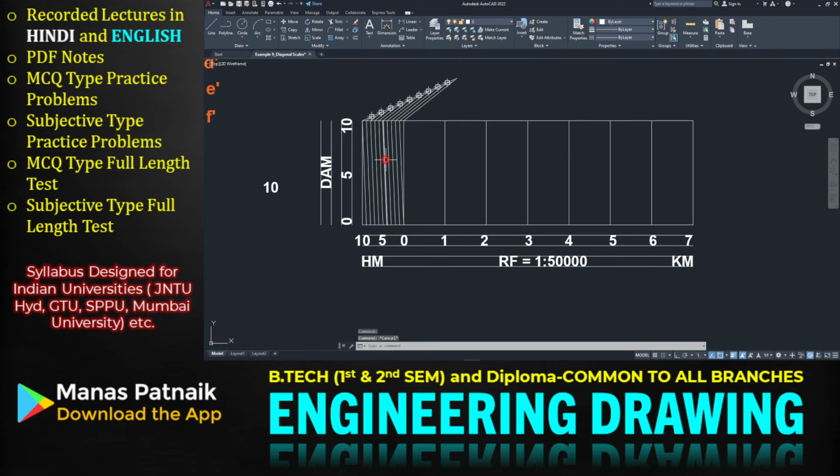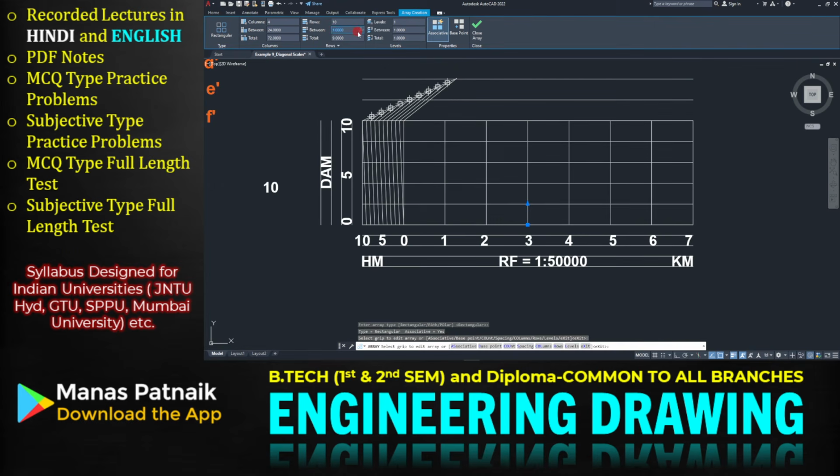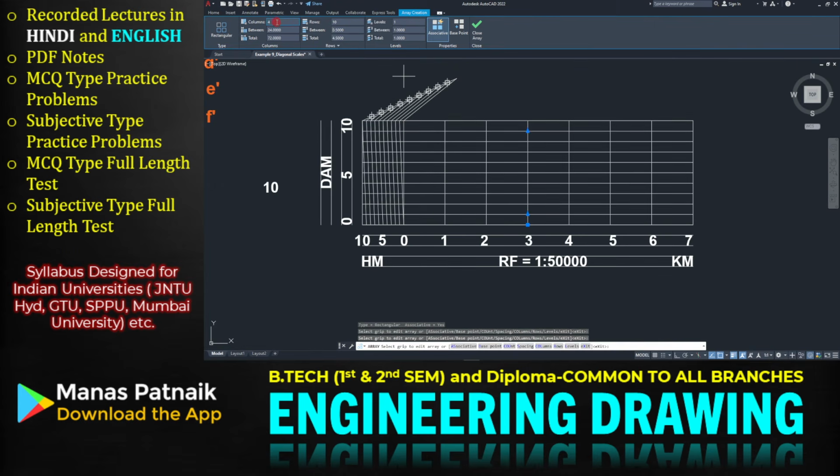However, I wish to unleash your AutoCAD skills. So we are going to use array, enter, and this is the object. We need to array in this fashion, vertically in the top direction. Hit enter again, rectangular, hit enter again. Now what we need is a good number of rows. How many? 10. And the distance between them is going to be 0.5. And the number of columns is going to be 1 single column.